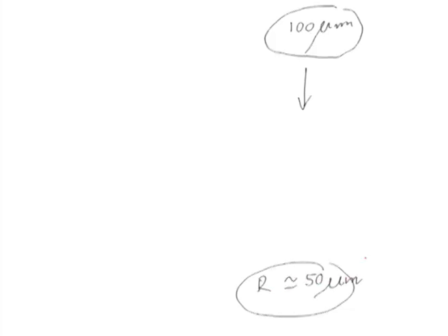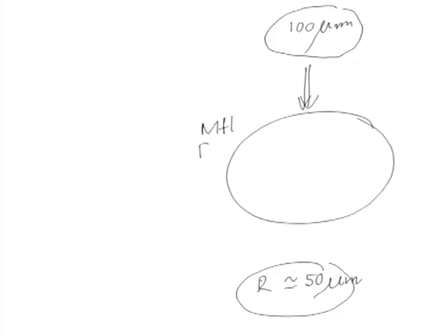Another important aspect in this pattern is the final finishing. Some of the castings may need post processing, say for example, to achieve some prerequisite surface finish, say from Ra equal to 100 micrometer to Ra equal to 50 micrometer. What I need is some reworking, or some material I have to remove from the original cast, which we can say is the raw casting.